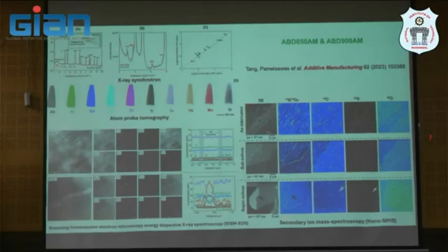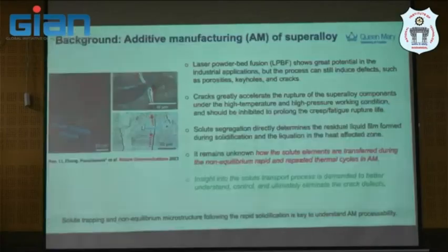If we do post-treatment at different sub-solvus or super-solvus temperatures, you can actually segregate out or homogenize some structure. And then this is quite a solid solution. If you see the profile here, yes, there's something across the boundary a little bit. But this is what we got, and then we know that, okay, this is different from the existing alloy.